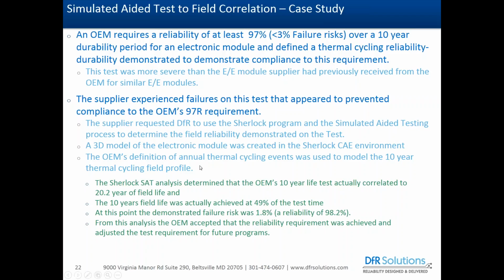We created the 3D model of their electronic module in the Sherlock environment, and we set up an annual thermal cycling event based on the OEM's definition of the annual thermal cycling environment they were wanting to design for over 10 years.